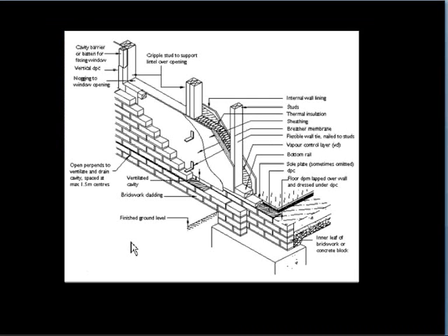Here in this sketch I've shown the construction in perspective, but primarily we've got the principal elements of the construction itself. We've got the vertical timber studs which provide the structural support, and they sit on a sequence of sole plate and bottom plate to form the bottom of the structure.